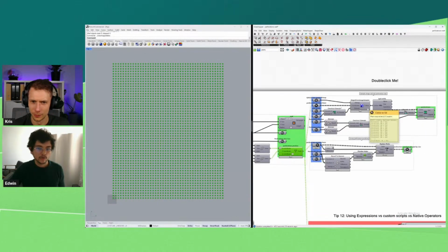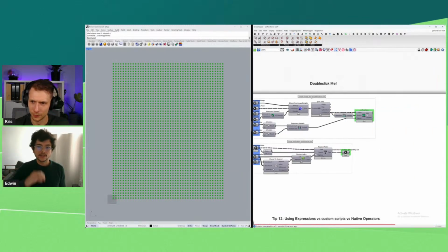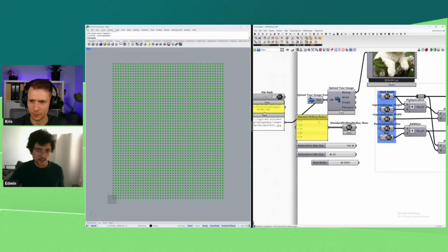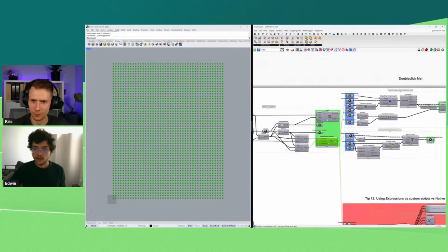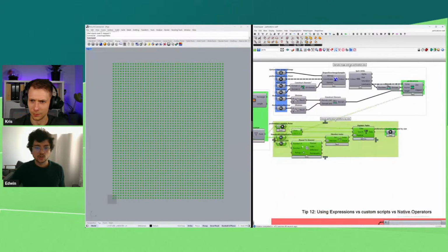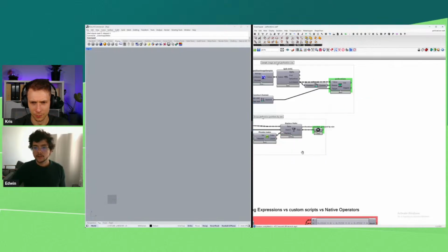And then I take the color of that bitmap in those coordinates, and based on the luminance in that point, I decide the size of the perforation. Now, in this case, I'm assuming that we have a machine with these standard drilling radiuses, so that's why I snap the sizes here to the closest standard size that we have.